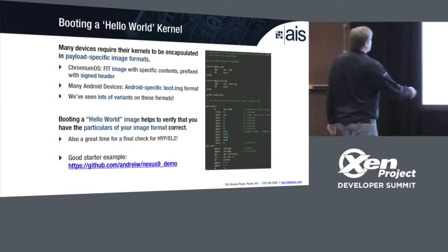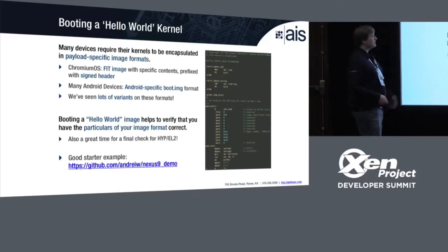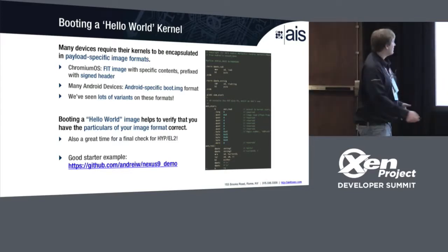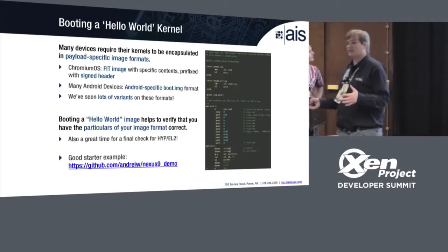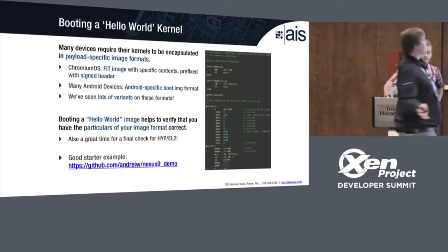All right. Once you compose your Hello World image, you can boot it and verify that you actually are loading the correct type of image. Right? It's also a great time to check for hypervisor or EL2 mode. That's as simple as checking the right bits on ARM32 in the current program status register, or the equivalent for